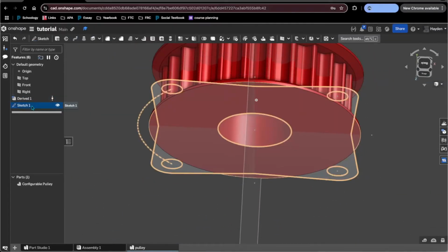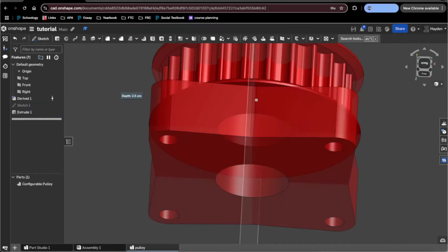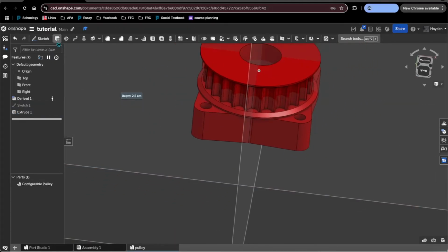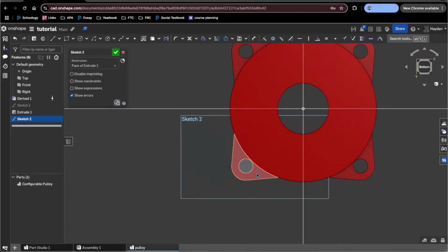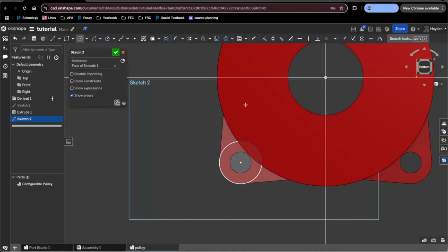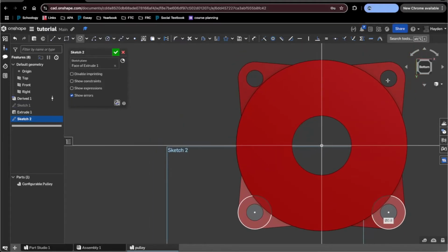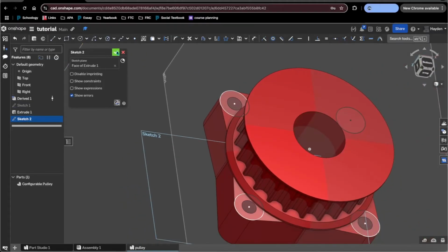And then, now we've done this, we're going to use the project convert function to project this bearing hole, and then we're going to extrude this to a depth of 1.1 centimeters, or 11 millimeters. Now we're going to create a sketch here, go to the bottom plane, and then 0.8 diameter of all these circles on the center point of each arc. It will automatically snap to this, so you don't need to worry. And then we're going to extrude this.